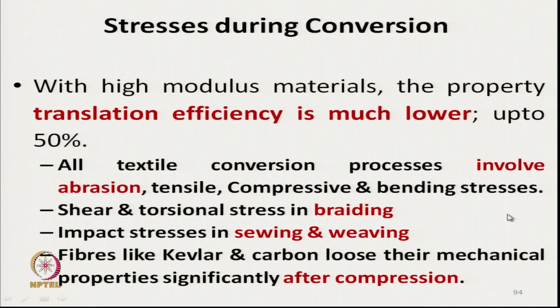So, these stresses effectively damage the textile material, these reinforcing materials. Shear and torsional stress is exerted during braiding, which damages the yarns or fiber. Impact stresses in sewing and weaving also damage. Fibers like Kevlar and carbon lose their property significantly during compression or bending.